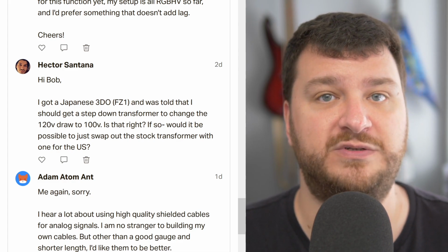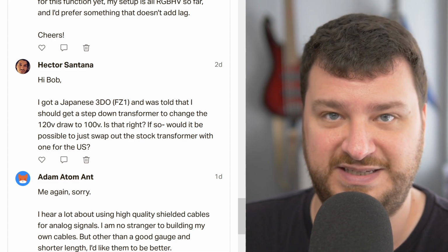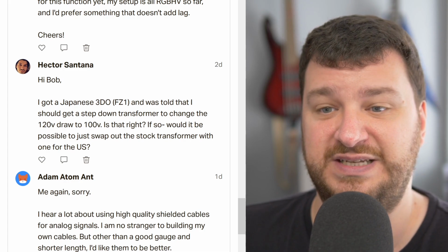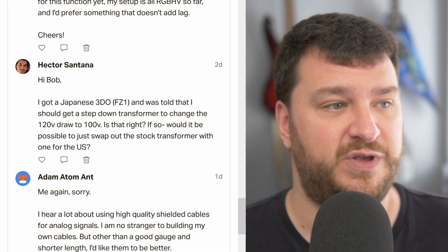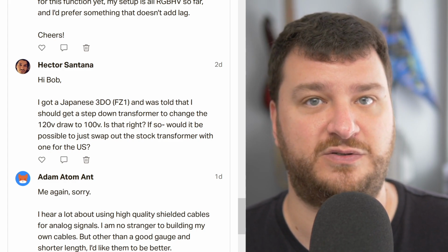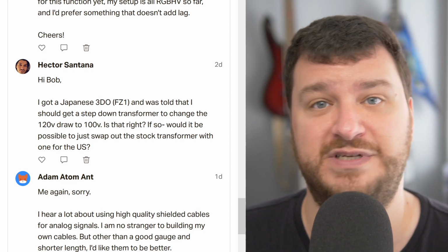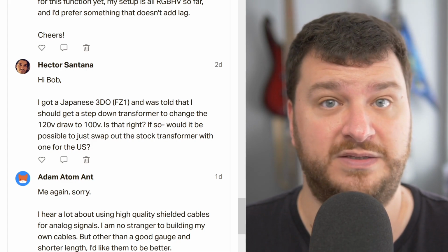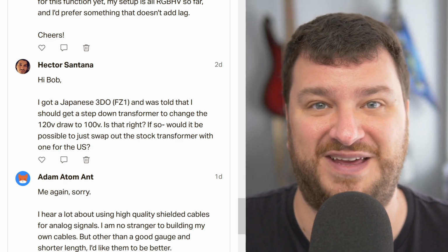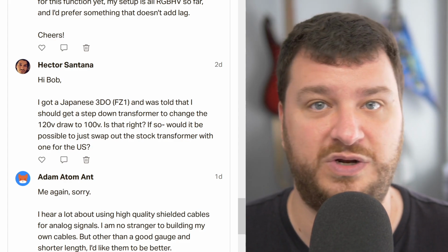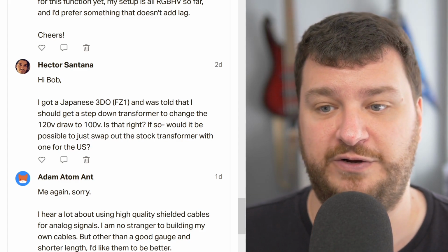The internal power supply in many consoles can possibly accept multiple input voltages. Some cannot. And in fact, it's not as easy as saying model X of this console can always do it. You really need to open it up, check the power supply, and see if there's any markings on it. Some power supplies say right on it, like 100 to 240 volts or something, and others say 120 volts only. Others, you just have part numbers and you have to look and see if anybody's figured that out.